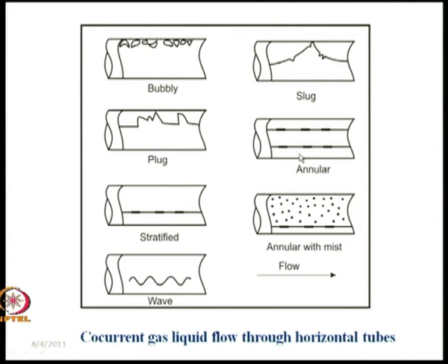Okay. Bubbly flow, which we had already observed there, annular flow, which we had already observed there. Generally churning is not very prominent, but churning can also be observed under these conditions. But all this bubbly, annular, slug, they are all characterized by one thing here, that is the asymmetry in the flow distribution, because the bubbles, the Taylor bubbles, as well as the liquid film, you will find the liquid film will be thicker at the lower side, and thinner at the upper side. And with gradual increasing of the liquid flow rate, we find that gradually the effect of gravity decreases and more or less there is a uniform distribution.